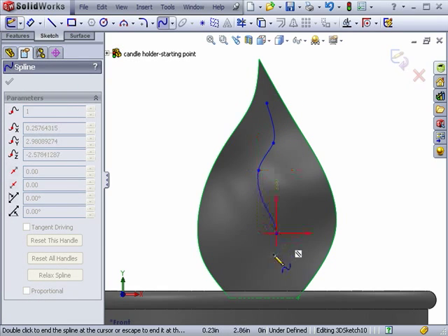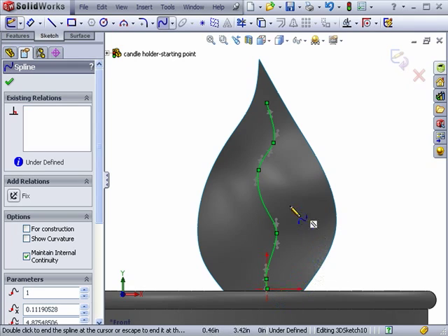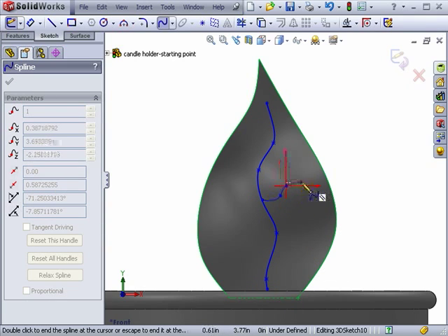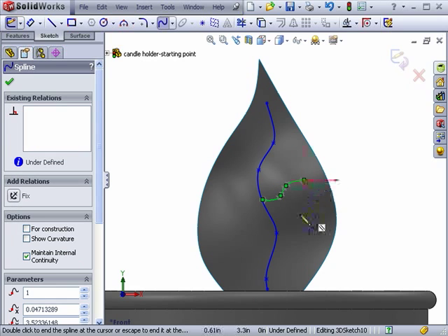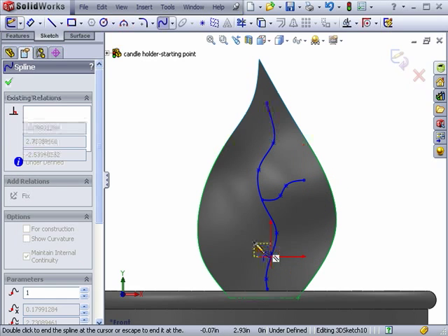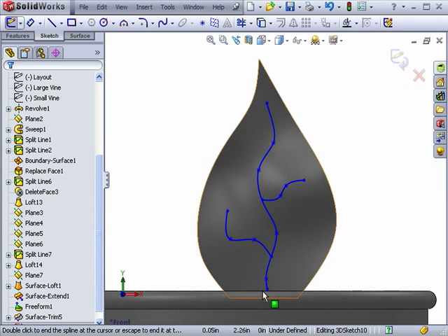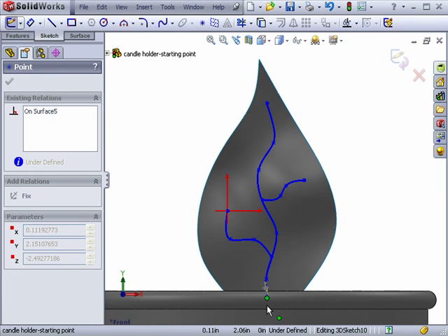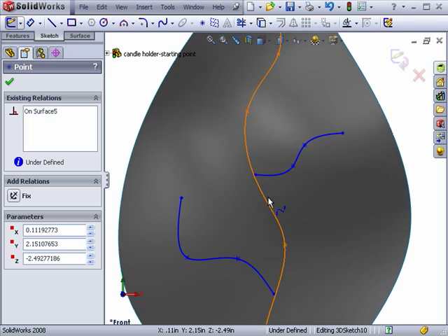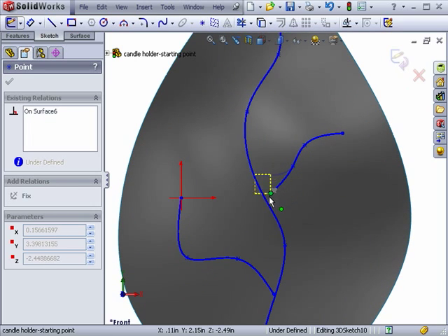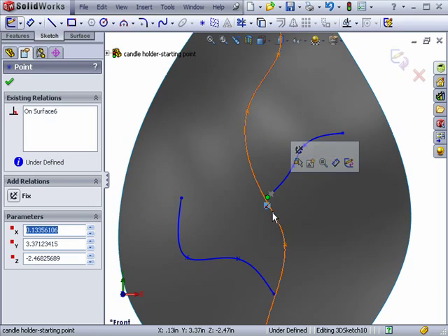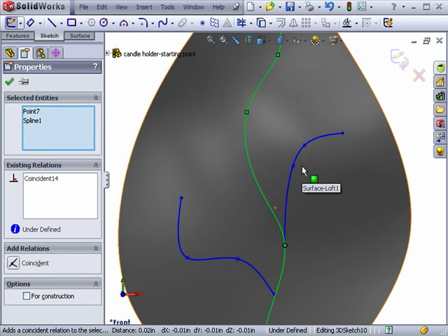Note that each vein in the network will require a separate loft feature, a plane, and 2 additional sketches to complete. Because of this, I'll keep the network relatively simple. I'll also be sure the branch veins are attached to the main vein. This might require manually adding a coincident relation.